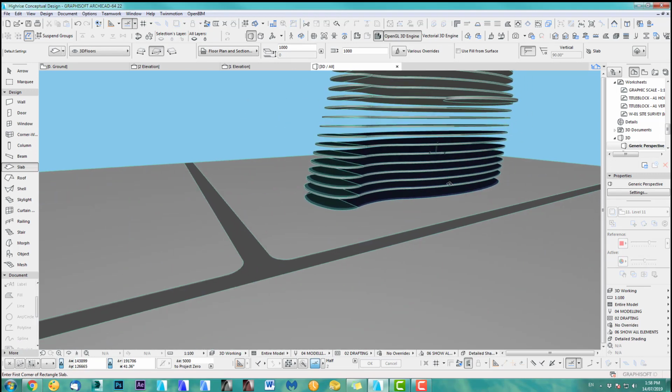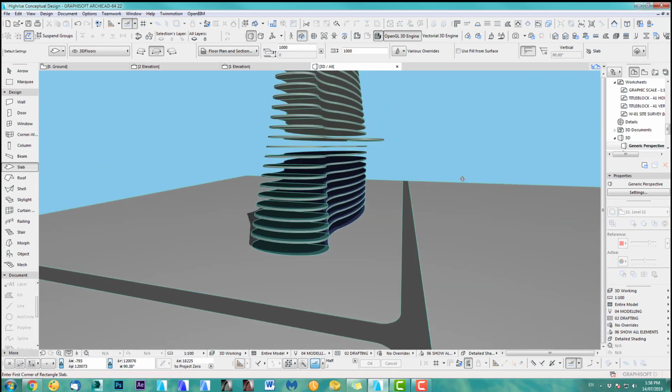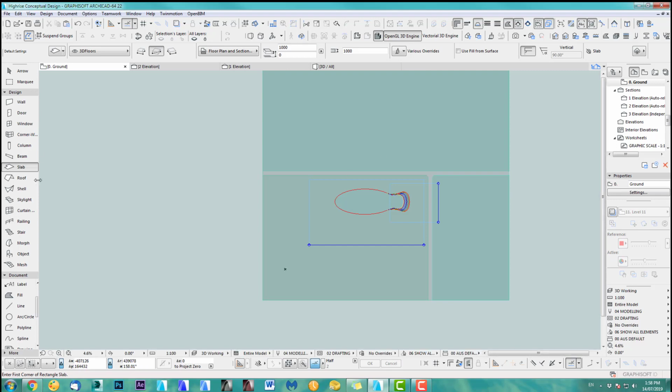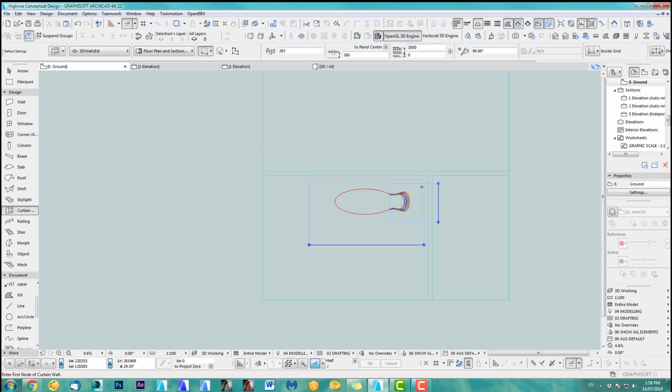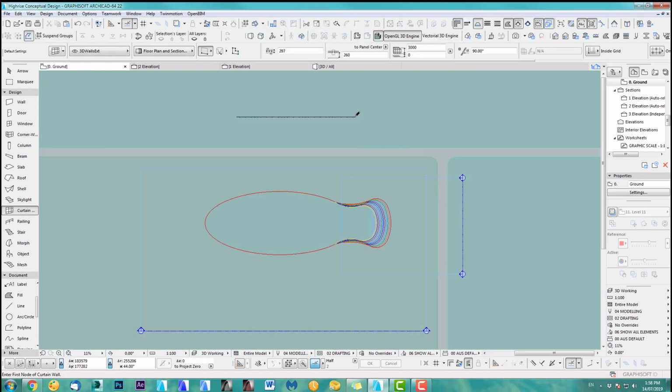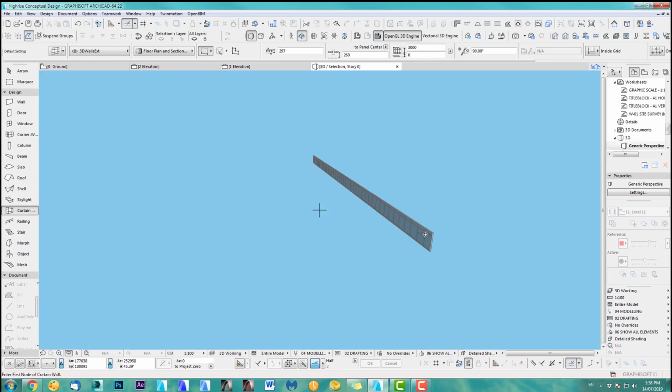Start up with the, I could use the curtain wall, but the curtain wall has a problem when you go on an angle and it's round like an ellipse or something, it will not step back. I'll show you. So this curtain wall works if you draw a straight line. I'll show you that quickly. So that's the curtain wall in 3D, looks great. And we can obviously select this and say, oh look, just make this 60. See, it's beautiful, I love it, but it only works on a straight curtain wall. So that's the problem, because obviously we got ellipses.